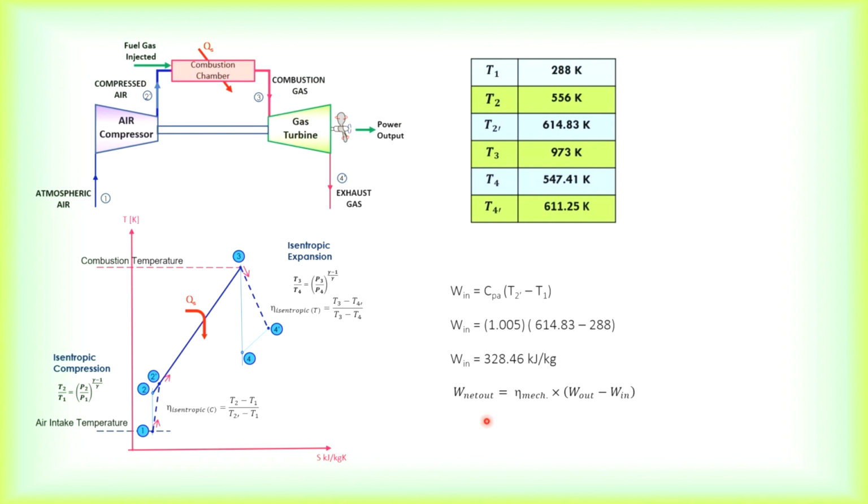That is why a mechanical efficiency is sometimes introduced. If no mechanical efficiency is stated, then we can assume 100% effective power transmission, so that means there's no loss due to friction. If there's a loss due to friction, let's say 2%, then your mechanical efficiency will be 98%.